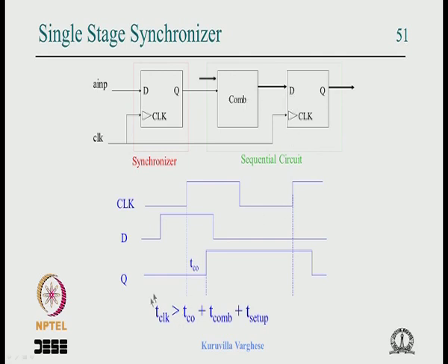So if the clock period is chosen properly, at the next positive edge, this input, that means the output of this synchronizing flip flop, will meet the setup time, and hold time, so there should not be a problem. And of course the input which is synchronized will reach this destination register with a latency or a delay of 1 clock period. So that's a penalty we pay,